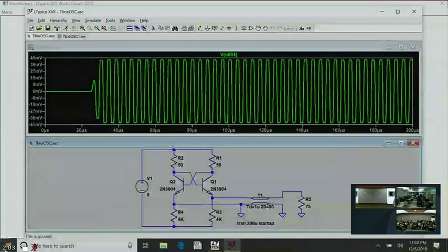And the reason is they're designing integrated circuits, and there's no way you can cut every feedback loop of an integrated circuit, spend 10 minutes on every Bode plot, and decide whether or not it's stable. There is one and only one way of telling whether or not an integrated circuit is stable, and that is to do a time domain analysis of that circuit and see if anything buzzes. And that's been the design technique for 30 years. That's why I don't do it for stability analysis.